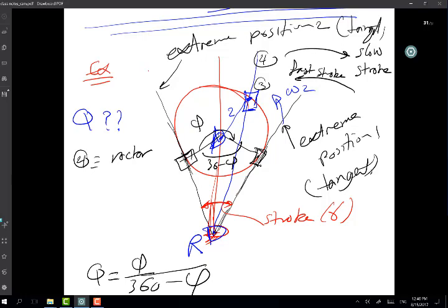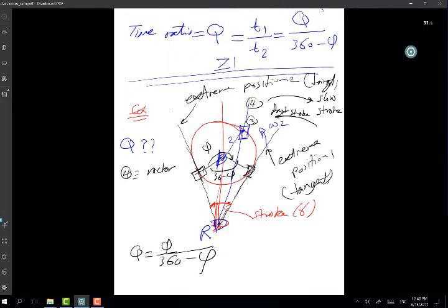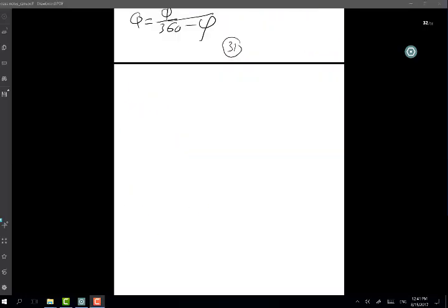Okay, so this normally is an exam question, in which direction the power is done or the job is done. You look at the direction of rotation and of the rocker or whatever, from right to left or left to right, and you say which direction corresponds to the slow motion, and you say the job is done from right to left or from left to right, based on the direction of rotation you have in the problem you're dealing with. So this was a very important aspect of linkages in general, which is the quick return action of the linkage.